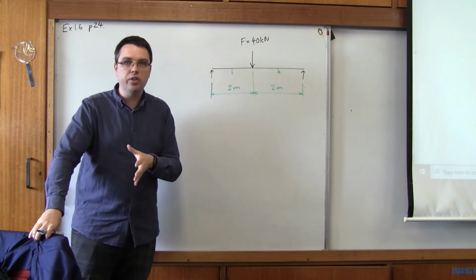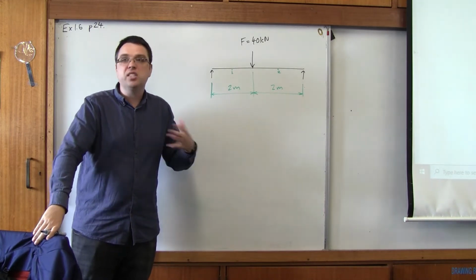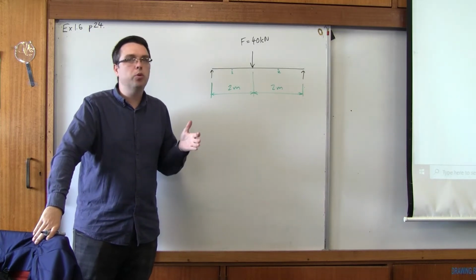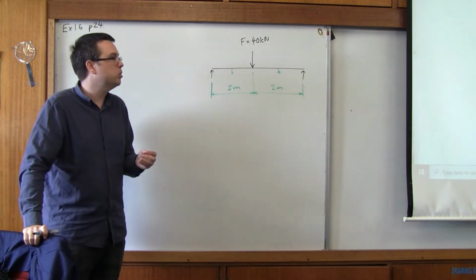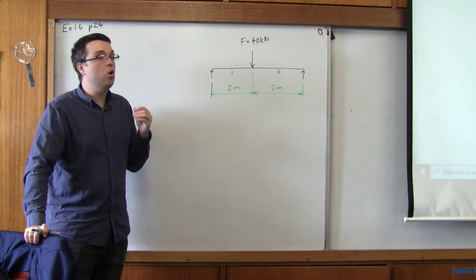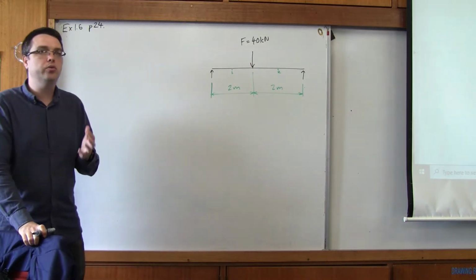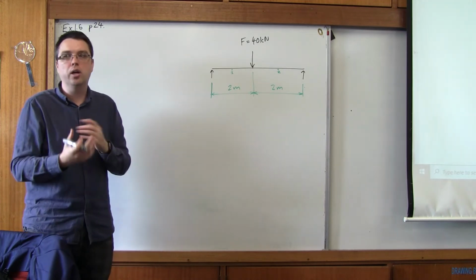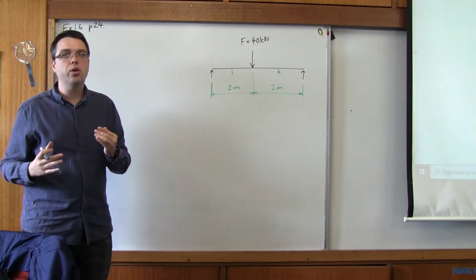In another video I've talked at some length about how, for steel beams, shear is almost never a problem. For concrete, shear is not usually a problem because of stirrup spacing, which I've gone into in a lot of detail in another video. But for concrete slabs, shear can be a problem, and that's why we have to have shear pads to prevent the columns punching through concrete slabs. But generally, shear is not how things fail.